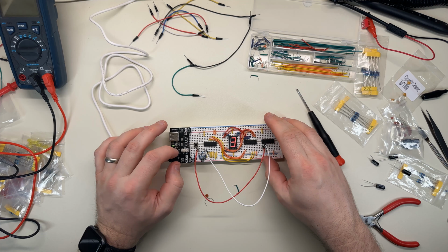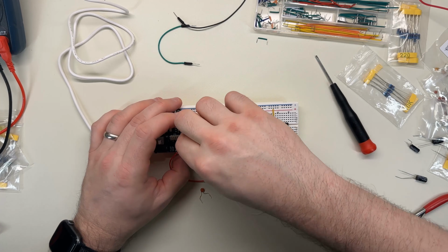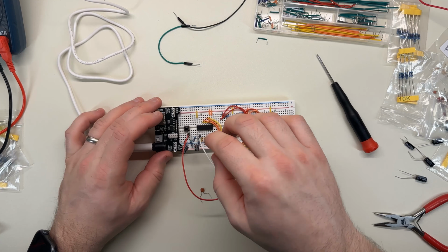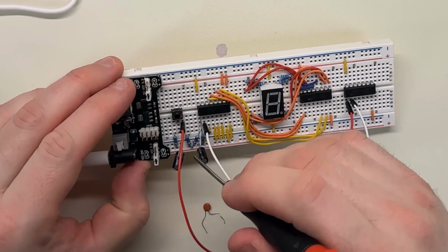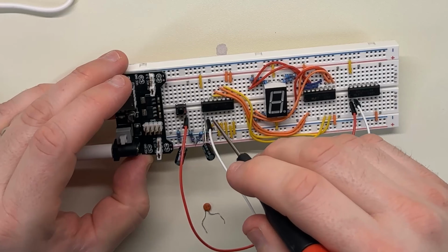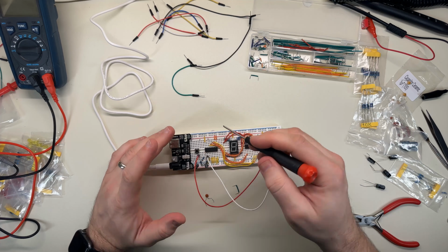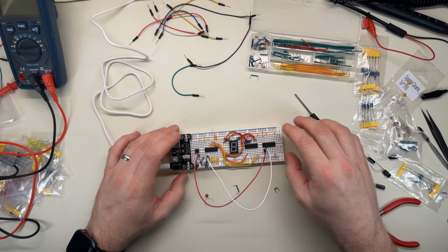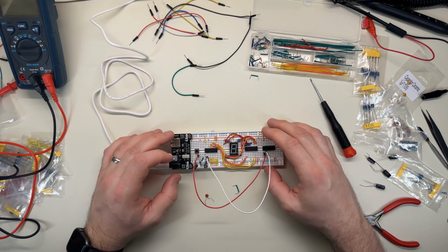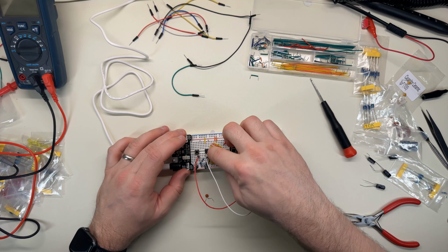Oh, look at that. I managed to get it to fail on camera. Excellent. Well, how about I'll just put a 10K in there and see what happens. Okay, I swapped out the 100K for a 10K, and it's connected, again, very difficult to see, but it's basically just connected across the legs of this capacitor. So it should mean that when the power's off, it's going to drain through here and just get dissipated as heat. Since this is 10K now, it should be about 100 milliseconds to discharge it 60%, I think, is how that works. So it should probably get it below the threshold.